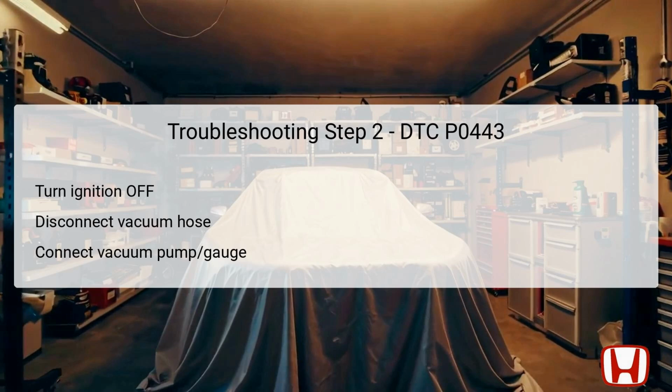result of this test. Following the results from Step 2, the next troubleshooting step involves assessing the PC-SOL line and the EVAP Canister Purge valve. Turn the ignition switch to the lock position to ensure safety before proceeding. Disconnect the 2P connector from the EVAP Canister Purge valve to isolate it from the system temporarily. This is crucial for further checks, ensuring no power is supplied to the component during testing.